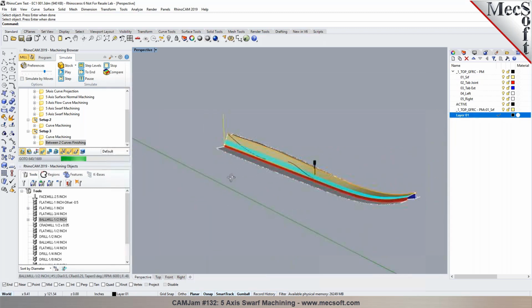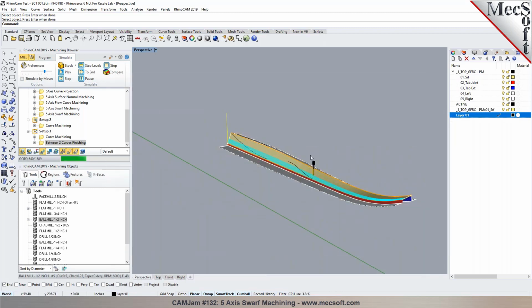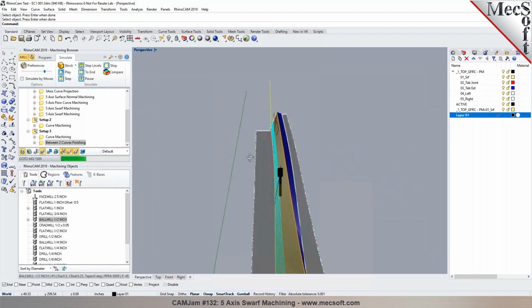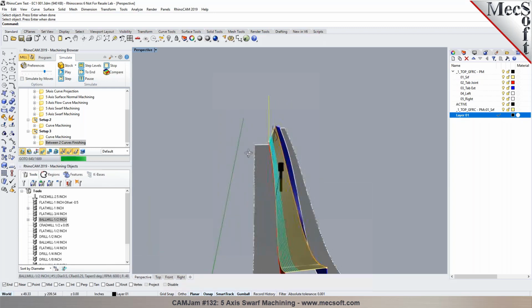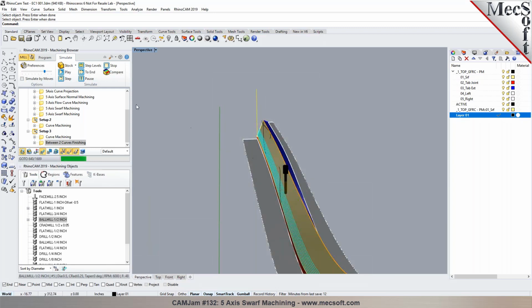That's great. One of the things you can also do is set up knowledge bases to automate selection of curves. You can put them in layers and automate them by applying selection rules in 2 and 3 axis operations very effectively. The selection rules in 5 axis wouldn't work well because you have to pick drive surfaces, wall surfaces, check surfaces. So the selection rules work very well in 2 and 3 axis operations. They are ideal for those applications.